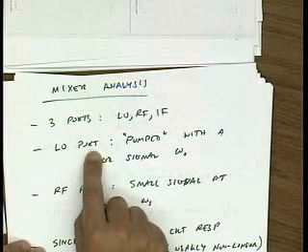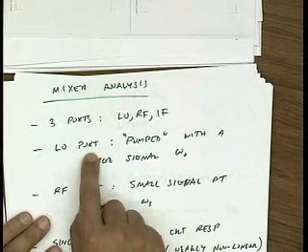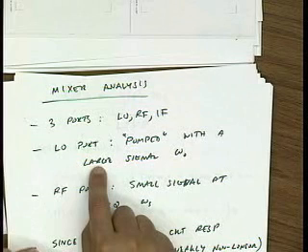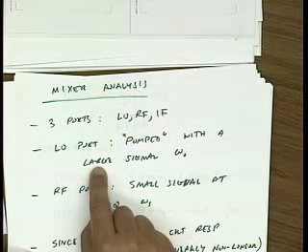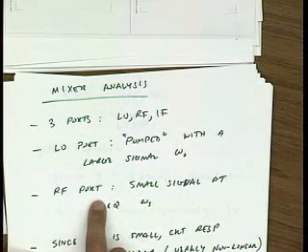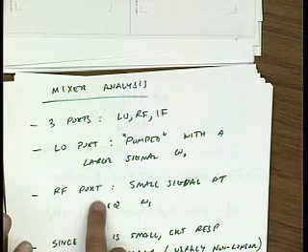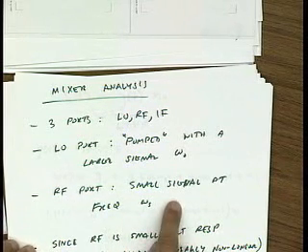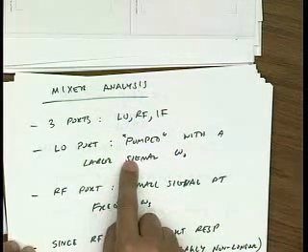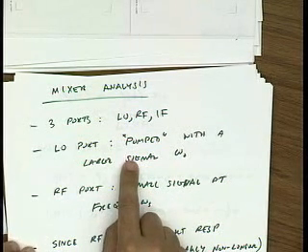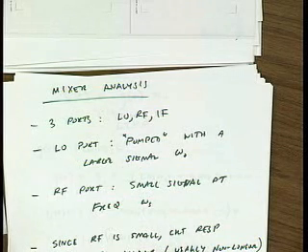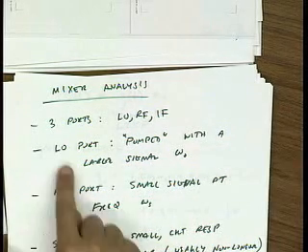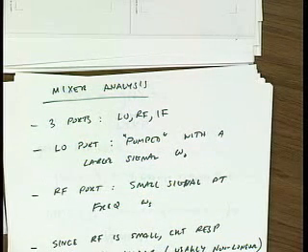We assume the LO is very strong, so it will actually periodically alter the operating point of our circuit. The RF, though, we assume is very small, very weak. So the RF port should essentially see a linear circuit, but it's a linear time-varying circuit because of the action of the LO port. As far as the circuit's concerned, from the RF port's perspective it's a small signal circuit, but from the LO port's perspective it's a large signal circuit.